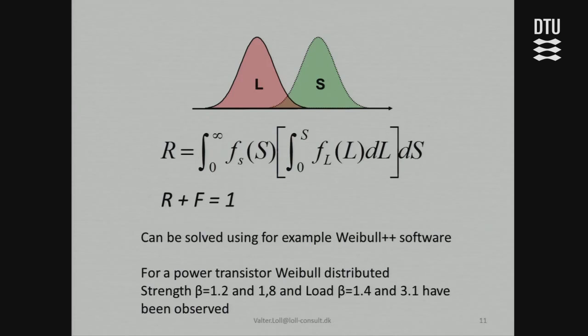So we can see if there are parts of the design which do not have the margin we need. Typically it's 2 or 3 details in the design which are not strong enough, and you just have to make them as strong as the rest. You don't have to make the whole thing stronger.